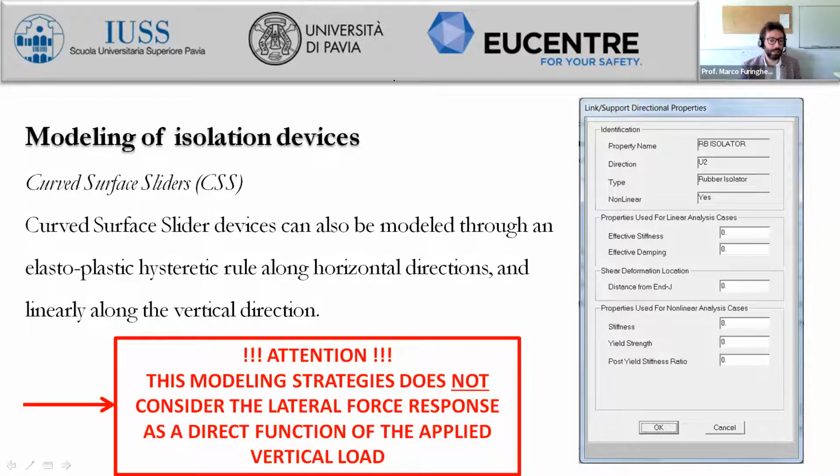So, okay, this is not so high if you just consider the overturning effect of the inertial forces, and you don't consider a significant vertical component of the seismic event. But generally, you have to at least remember that your results will be slightly affected from that.